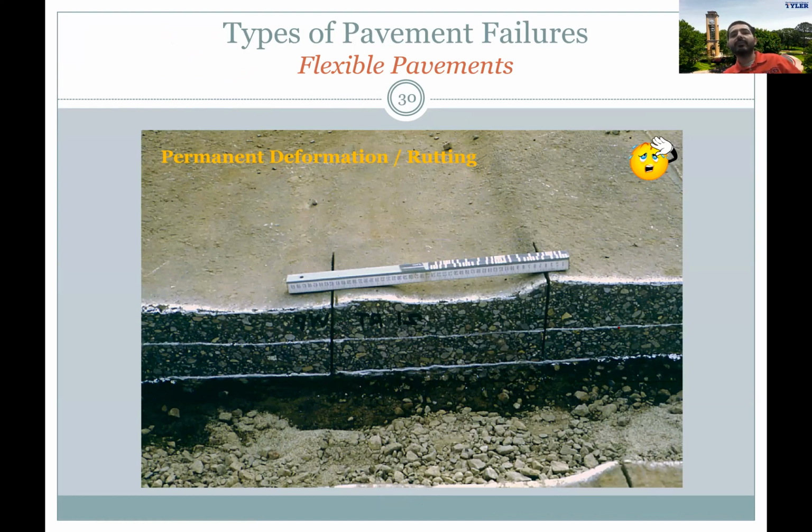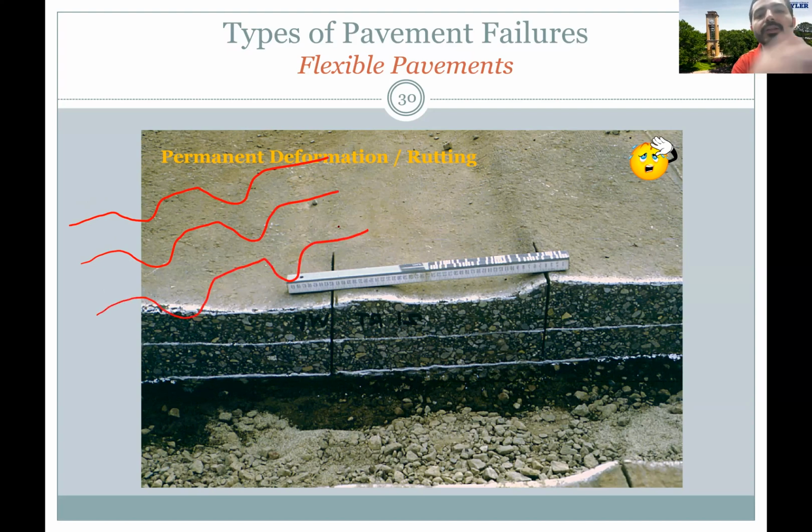This is where I identify rutting or permanent deformation. Sometimes rutting happens because of issues of the surface layer, or it can be because of the subgrade layer. So how can I distinguish this? Actually, by doing a trench study. This is what we call a trench study. I have to go to the field, cut through, and I want to see one of two phenomena. You are either going to see something like this, so the entire structure is having the deformation like this, or you can see something like this.